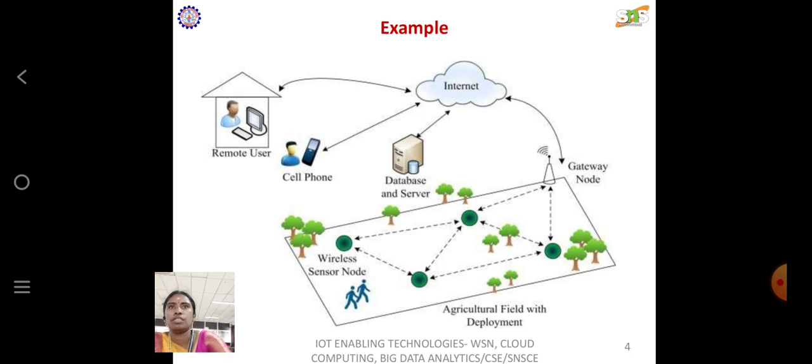And then power consumption. Many of the challenges of sensor networks revolve around the limited power resources. The size of the nodes limits the size of the battery. The software and hardware design need to carefully consider the issue of efficient energy use. Data compression might reduce the amount of energy used for radio transmission, but use additional energy for computation or filtering. The energy policy also depends on the application. In some applications, it might be acceptable to turn off a subset of nodes in order to conserve energy, while other applications require all nodes operating simultaneously.